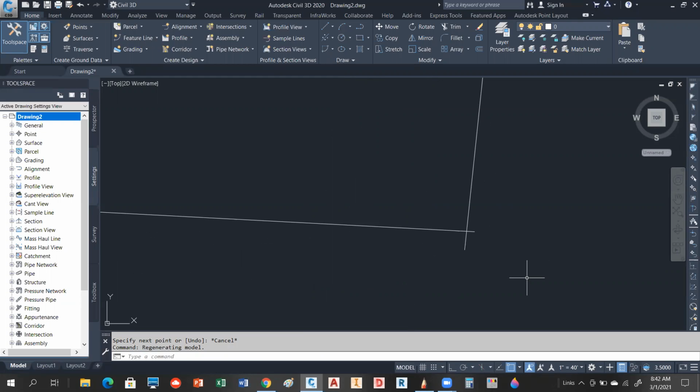So we're going to fix this because this is a really small, minute thing, but I don't want it hanging out there. So you do have to recognize by trimming these, we're going to change the distance, but it's so minuscule. What I'm doing is I'm holding the direction and messing around with the distance a little bit. So you could use a trim. I like fillet. Fillet's a really nice thing to use. I just type in F for fillet, set your radius equal to 0, and then you just select the two lines, that line and that line, and that'll trim it up.